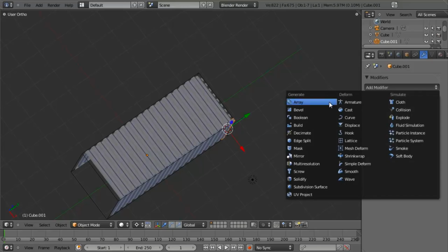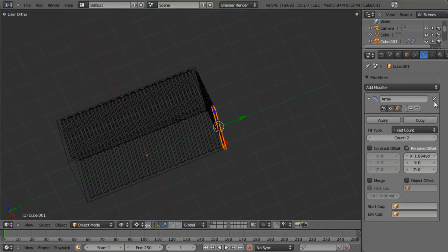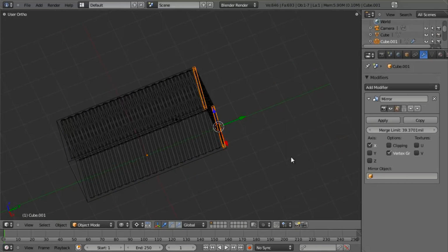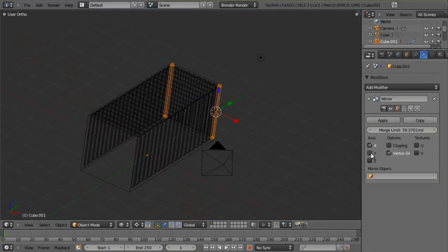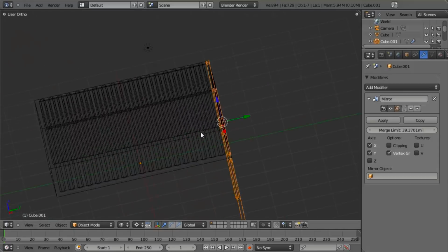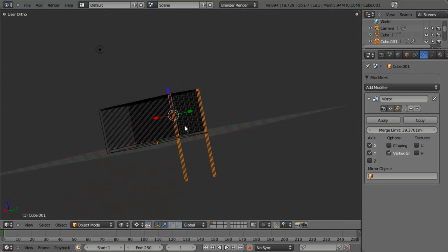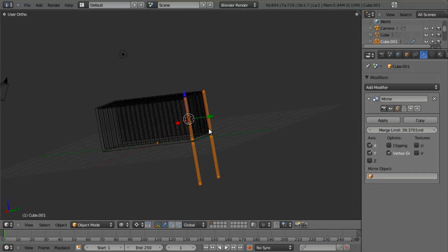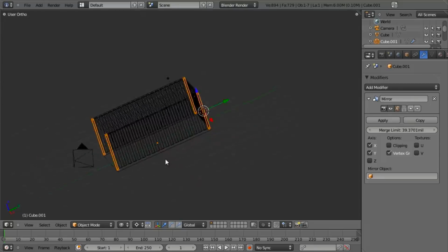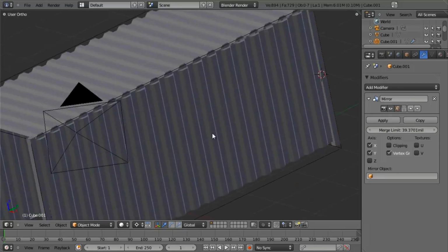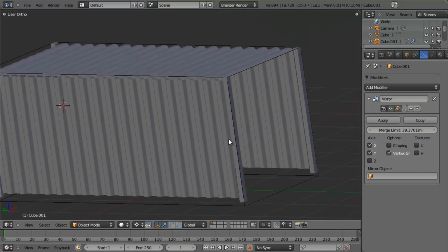And since I've got my origin point still locked right in the, oops, that's an array. I've still got it locked right in the center, I can go ahead and mirror it along the Y and the X axis, and it will just flip perfectly. But you'll notice something in that currently it's flipping along the Z axis when I tell it to be the Y. So we need to hit Control A and apply the rotation. And then it will immediately just flip over to the other side. There we go. Let's save everything.